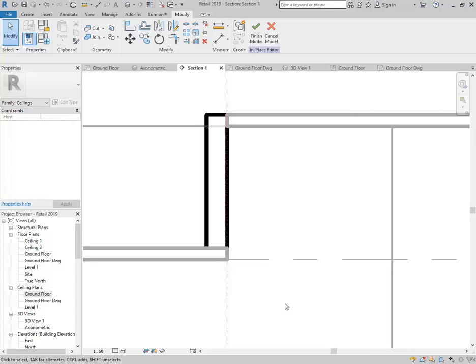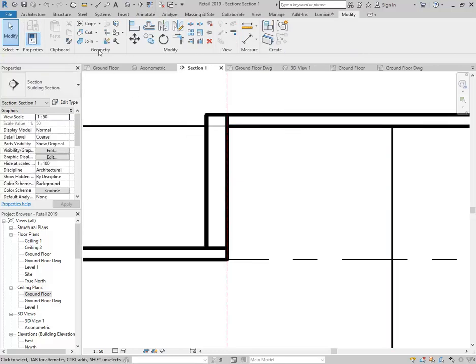You might think, well, okay, that's all right, but it's a bit messy because it's not joined to the other ceilings. So I'm now going to finish this, and we can still use the join tool. This isn't essential, but it's a nice thing. Choose the previous ceiling, and then my new extrusion, which is still a ceiling, and join that to the other ceiling, and it looks like one continuous thing.